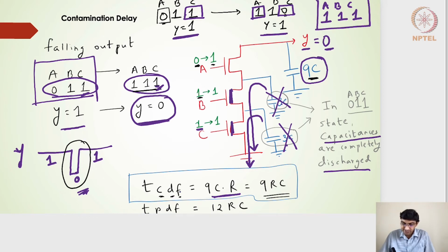Right? And I think this contamination delay is one of the design parameters that we need to consider, especially while designing sequential elements. So once we have flip-flops or latches, and in between the combinational circuits, followed by one more sequential element, we have to consider the contamination delay so that timing violations don't happen, and the timing violation is characterized for a particular sequential element, right?